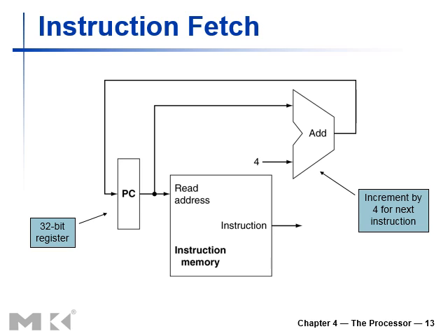And in the MIPS architecture of the single cycle processor, we've got the instruction memory that is responsible for holding the machine code. If you remember the x86-64 architecture, the memory is segmented, and the code segment is the dedicated segment that contains the machine code of our program. We access that with the help of the code segment register and instruction pointer, which provide the machine code through the bus interface unit into the instruction queue, and that is later processed by the execution unit in the processor. So the same is the case here. We've got the machine code stored in instruction memory, and these are the basic components of the modules that are utilized while fetching the instruction. So if you see, it basically consists of three major elements.